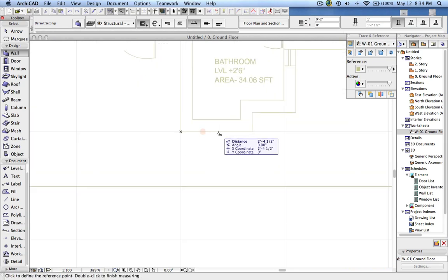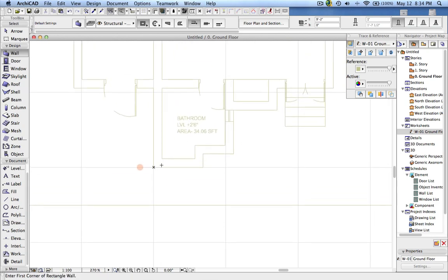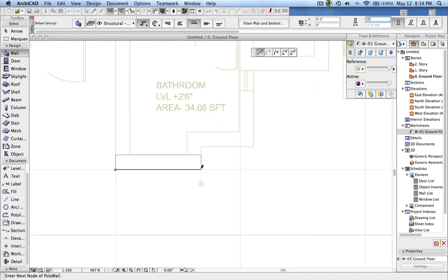Let me measure the distance, 9 inch. Now you can see that even though we imported this drawing using the drawing tool, as an AutoCAD drawing, you can still snap to the points. I use the polyline method, say 9 inch, and now it properly fits and snaps to the points. You can use the tracker to check whether the distances are correct.